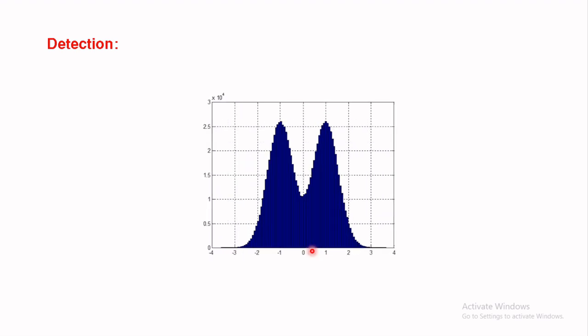This figure shows what happens if we have a lower signal-to-noise ratio, or a higher noise power. The receiver can do the same thing. It can define a decision boundary and decide that whatever is received here is 1 and whatever is received here is 0. But here we can notice that there can be some errors. For example, we may transmit 1, and because of the noise, this 1 can be translated to this position because of the effect of the channel.